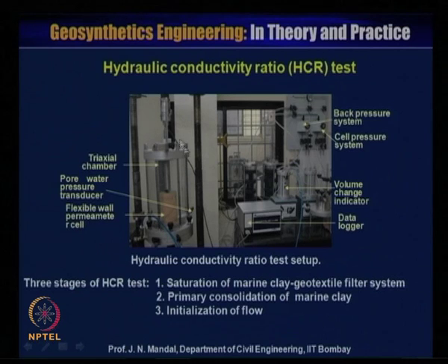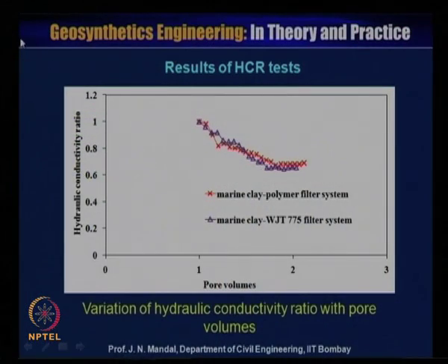When you perform this hydraulic conductivity ratio test, there are 3 stages of the HCR test. First, saturation of the marine clay geotextile filter system. Second, primary consolidation of marine clay. And third, initialization of flow. So, this also has been described. Here I am just showing some results of the HCR test.